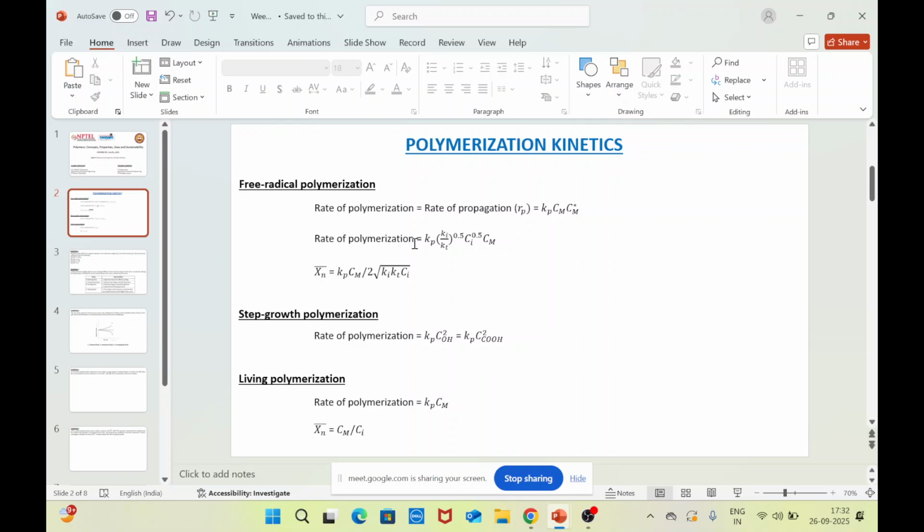Since cm star is going to be an intermediate in the reaction, and since we cannot calculate the concentration of cm star, which is going to vary with time, we are supposed to represent cm star as a function of values that we know. This is the basic of chemical reaction engineering. Certain steps, or the rate determining step, will have concentration terms of intermediates that get formed during the reaction.